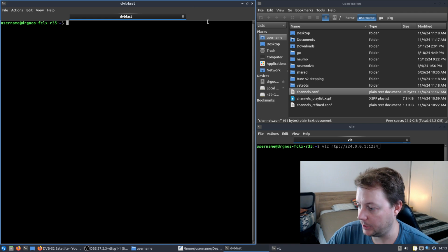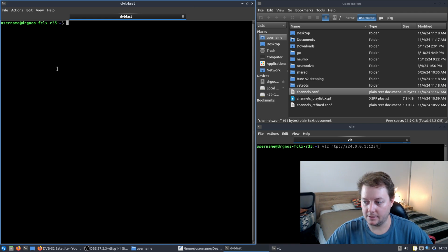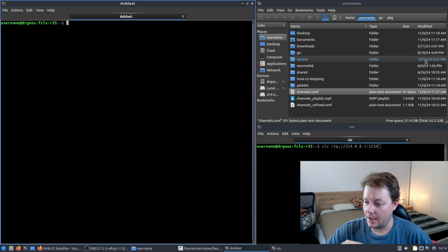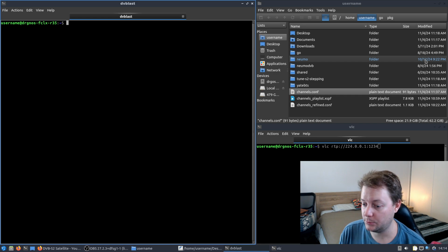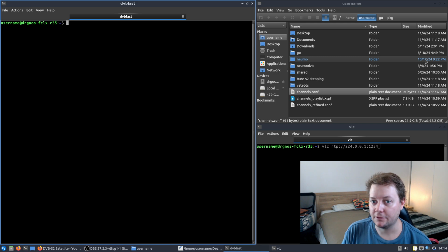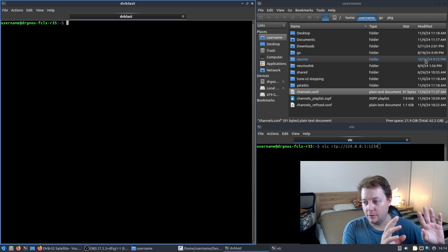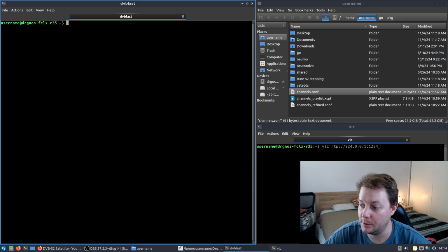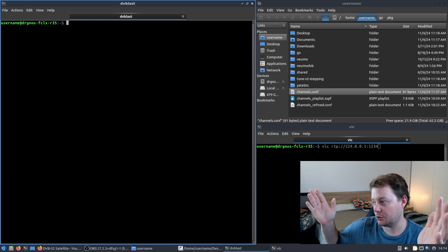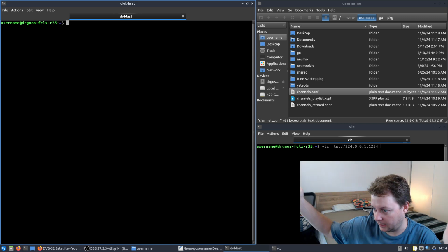So I've got a universal LNB, guys, which is the stock standard LNB that DVBlast uses. So I don't have to configure my LNB settings because it just uses universal as default. If you're not using a universal LNB, like you may have a 10750 local oscillator or a 10700 local oscillator or something, you'll have to send the binary the H argument and then figure out how to do that. But most people use universal LNBs, which means they can cover the entire spectrum from 10700 megahertz to 12750 megahertz. That's the entire Ku band range.